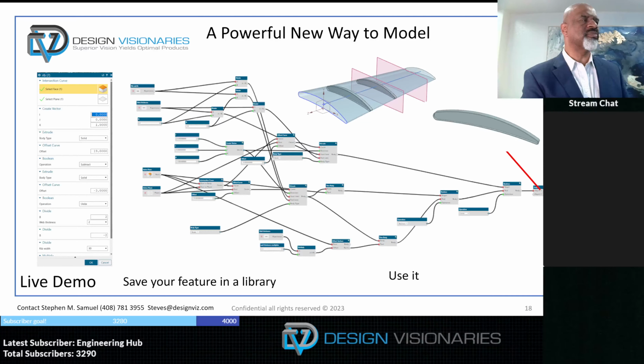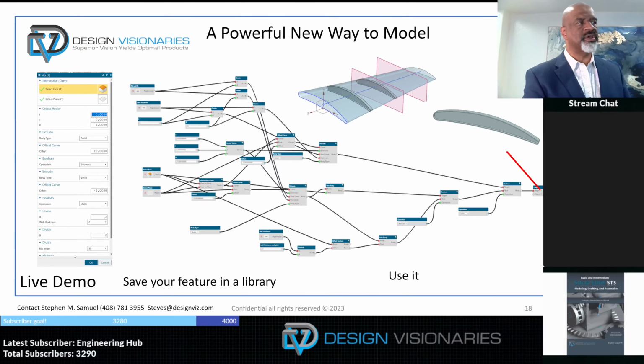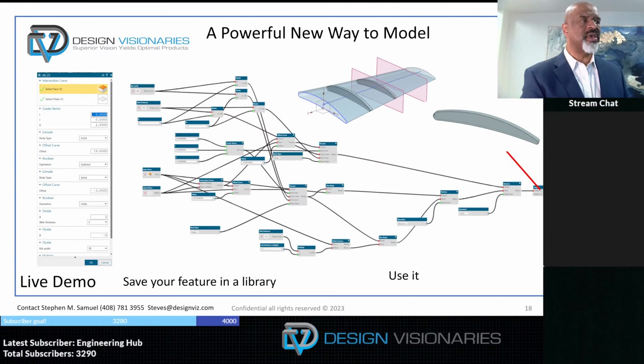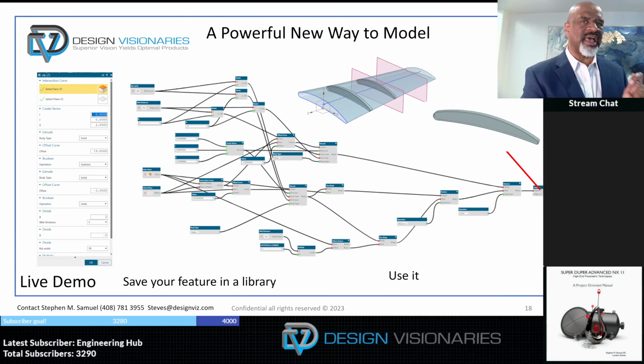Another example is from the aerospace industry. In many cases, if you have some sort of airplane wing or a flap, what you do is you bring in your OML, your outer mold line surface, and then you have to start making ribs. Well, this little program that it took me about 15 minutes to put together with all these little programming blocks basically has you select the face, the OML, the surfaces.